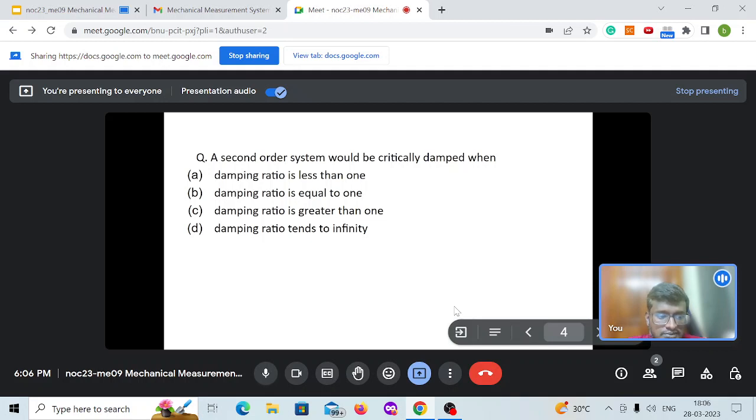And for underdamped, you will have small overshoots close to critical damping. At very low damping ratios, you will have higher overshoots, and the oscillation can be large. It will take longer to reach the steady state, or the error less than 5%, or whatever error you require. That time can be longer for a less damped or undamped system. So the answer is damping ratio equal to 1.